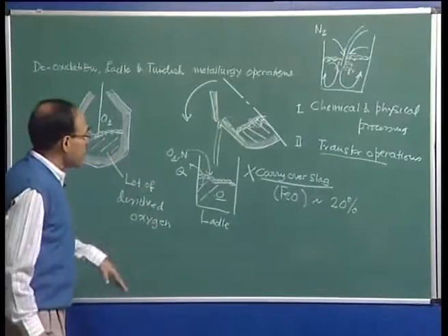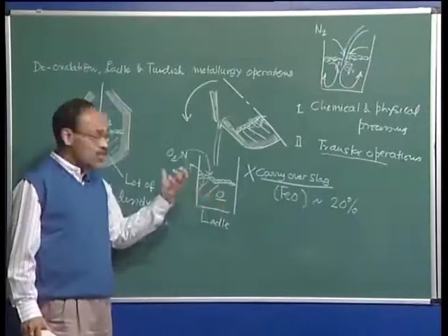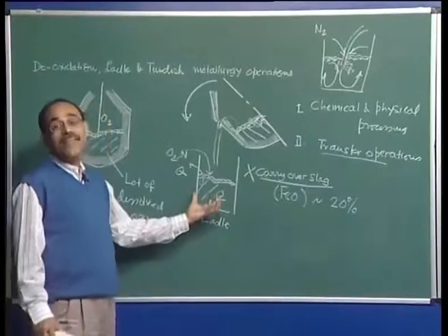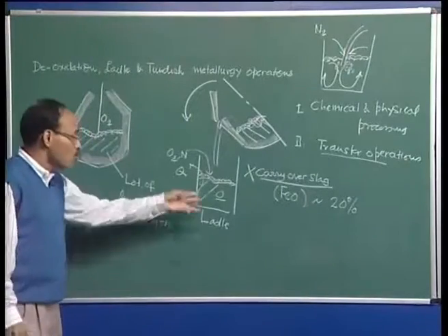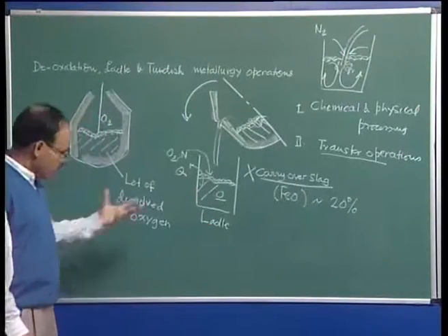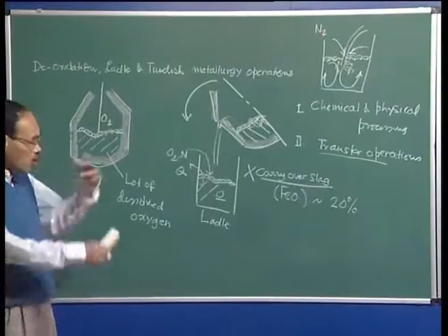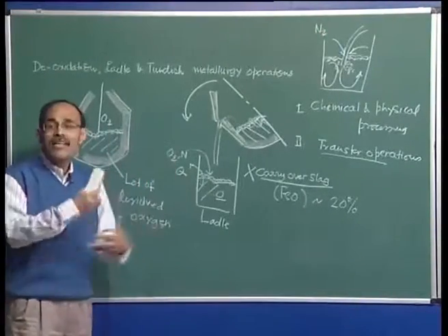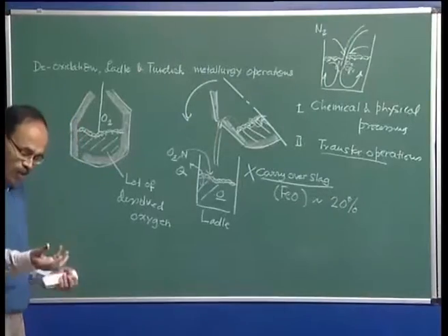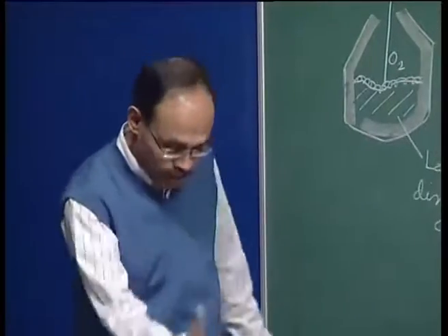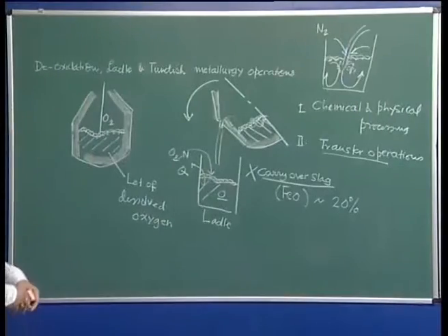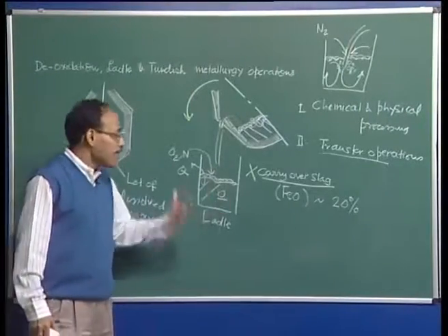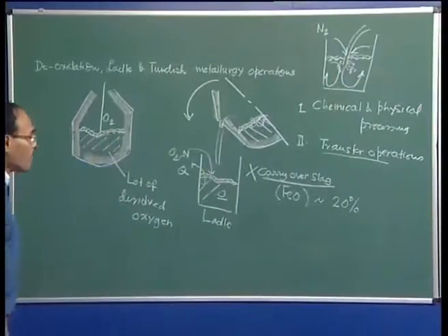We must understand that during the tapping operation, an extremely intense hydrodynamic stirring is available in the bath itself. So, now if you add some elements which are going to react with the oxygen in order to take away the oxygen from the bath, those elements can melt and dissolve in steel very quickly. For example, if you add a drop of potassium permanganate in that bucket, on which you can do an experiment in a bathroom, you can see that the potassium permanganate will dissolve in the bucket of water very rapidly, and the same happens in the steelmaking ladle during the furnace tapping operation.